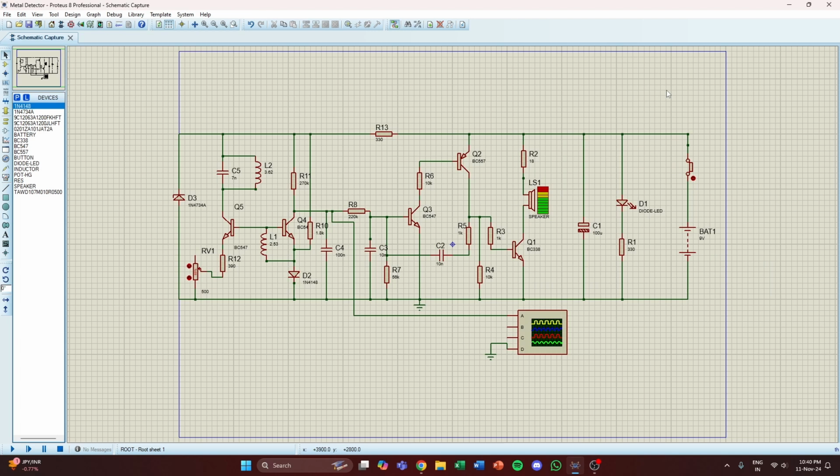The voltage it produces turns the first transistor on harder, and thus the waveform produced by the tuned circuit is increased. Since the resistance of the pot is minimum, the amplitude of the waveform will be a maximum, and this will have the effect of turning on the second transistor, so the voltage on the collector will be very low.